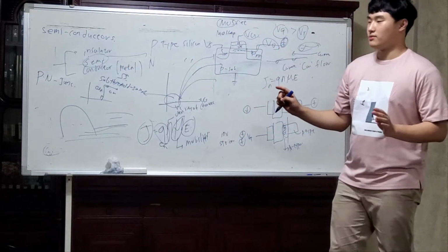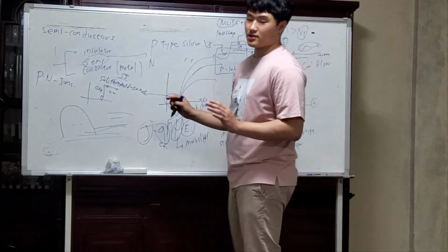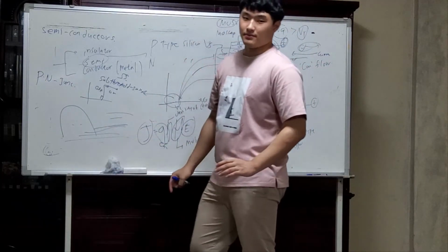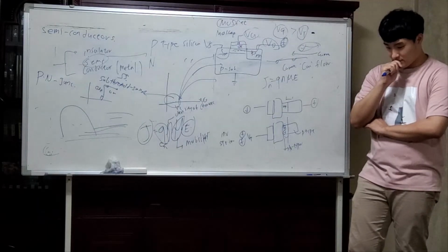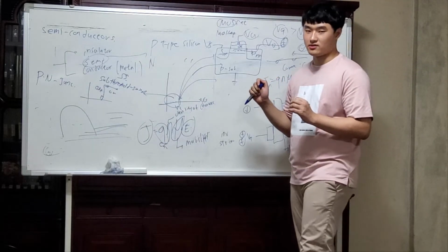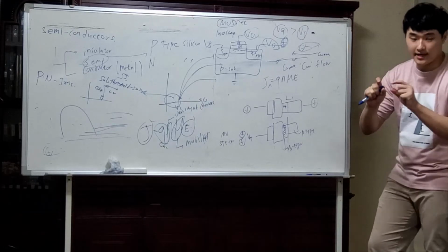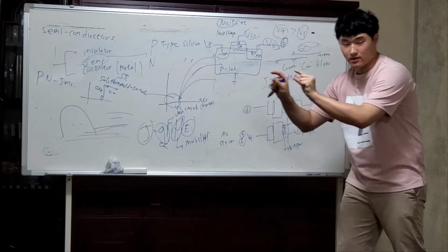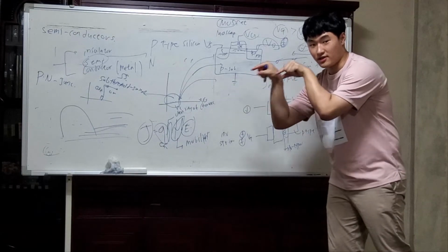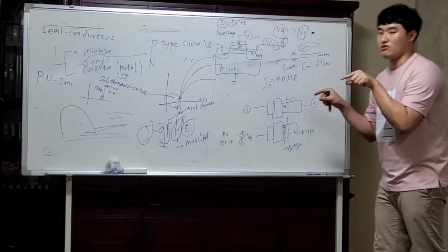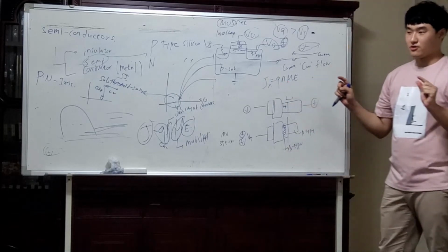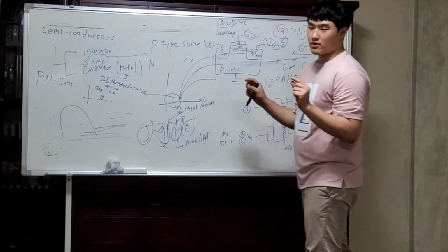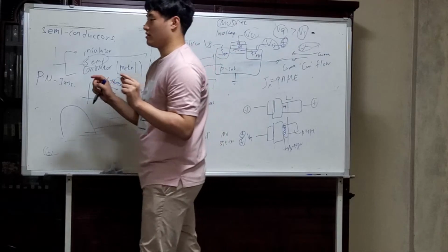Even if the voltage is under the threshold voltage, maybe by the diffusion effect, a few carriers can move from one side to the opposite side, and this will make current flow, and it will make the device consume power inefficiently.